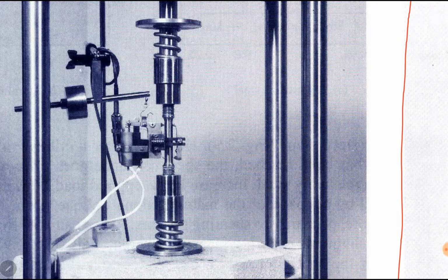We can see the ultimate strength also, it is different for different grades of steels and different after different heat treatment and alloying processes. But we can see that the slope of the initial line, this line, it is same for all of these steel materials. If the slope is same, it means E is same. Modulus of elasticity is same. Modulus of elasticity is slope of the stress strain curve in the elastic region. So slope of the initial line is same for all kind of steel, iron grades here.